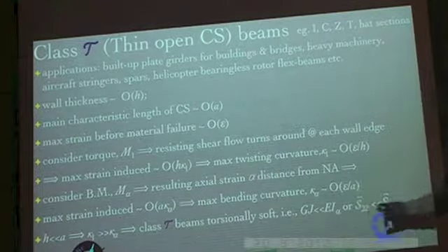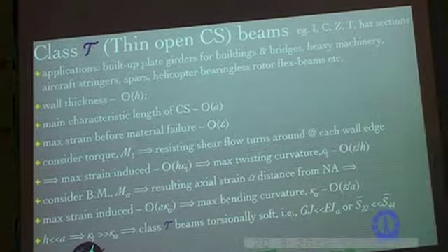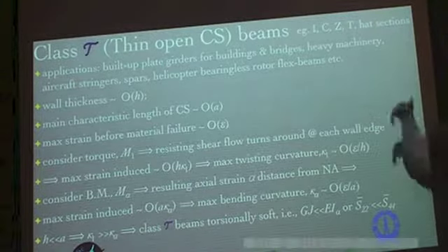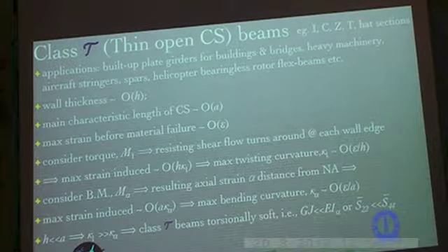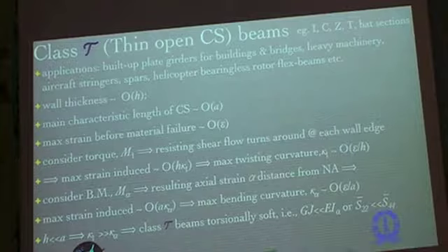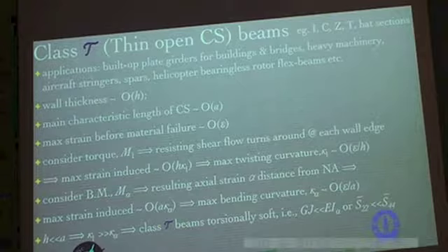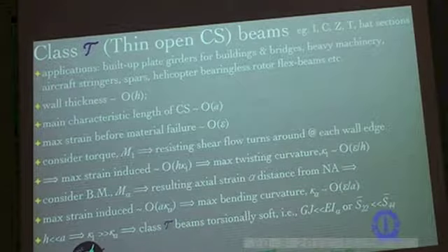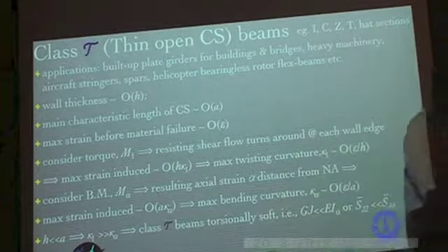So in the case of your 4x4 matrix, the classical zeroth order approximation that we have, which holds for all classes and therefore for the T class as well, S22 bar is much smaller compared to S44 bar, because in this matrix, 22 refers to the quantity associated with this and 4 is basically associated with this particular thing, which is about the thickness direction. Basically, this is the kind that we are talking about. But here, of course, we are talking of a thin-walled open cross-section, not a strip. So both kappa 2 and kappa 3 are of the same order of magnitude.